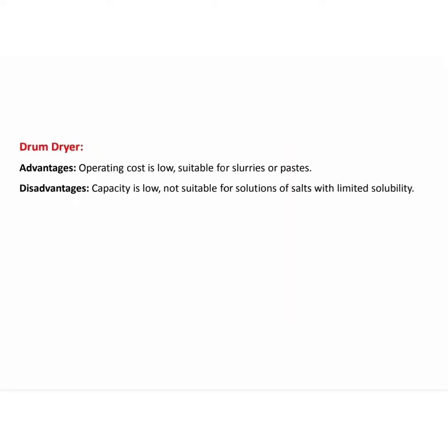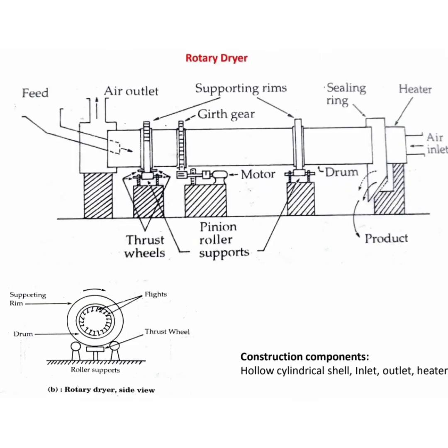Advantages of drum dryer: operating cost is low, suitable for slurries or pastes. Disadvantages of drum dryer: capacity is low, not suitable for solutions of salt with limited solubility. Now let's see rotary dryer.